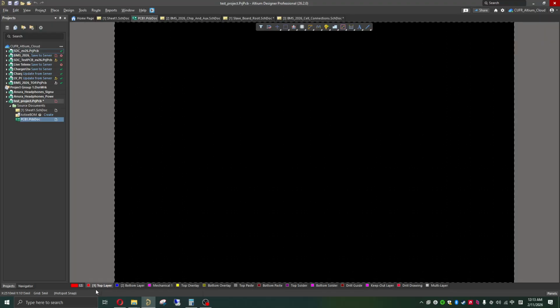On the bottom are different layers, and basically the way I want you to think about this, which is familiar for anybody who's done IC design, is that you're laying different layers of copper on top of each other when you're working on your PCB. So you define the board shape, you define the dielectric and everything, and then you're putting copper on top of copper, and you create vias that route through these different levels and connect stuff together. But like any type of technology, we have to define what we're working with. So let me show you how to do that.